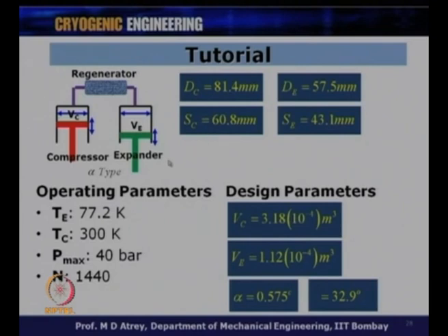It also depends on how much area is available for your cryocooler. If the space available is going to be smaller and smaller, then you might allow it to go for higher pressures in that case. However, the parameter which is not being considered over here is the mechanical design. It should stand the mechanical design, that means diameter, thicknesses etc. should be able to stand all these stresses generated because of this higher pressure.